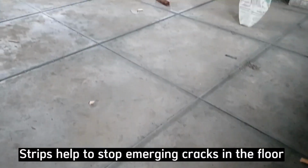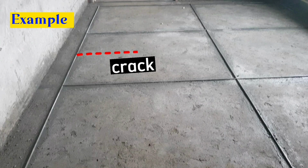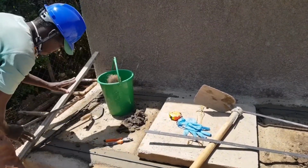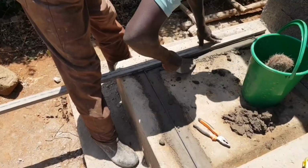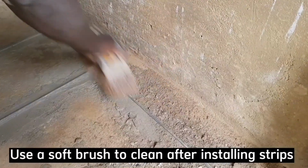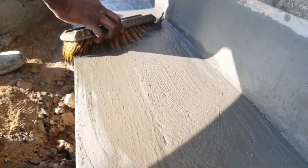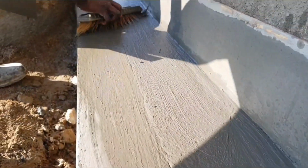These strips help to stop emerging cracks in the floor. For example, when a crack starts from here, as it extends to this direction, the crack meets this strip here and it stops here. That is the main purpose for these strips. After fixing all the strips, use a soft brush to clean all areas before casting terrazzo. This brush is crucial because it helps to spread evenly the surface when the mix is still wet, so that the top surface will be relatively flat on drying, hence making the grinding process so easy.